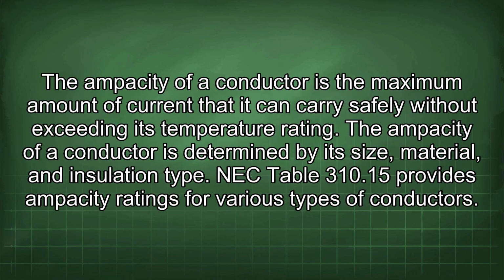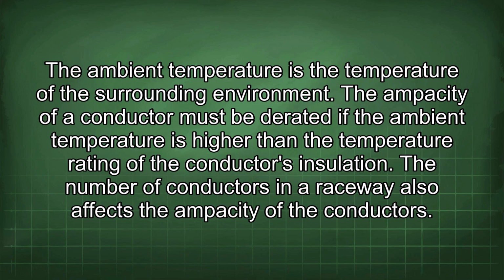The ampacity of a conductor is the maximum amount of current that it can carry safely without exceeding its temperature rating. The ampacity of a conductor is determined by its size, material, and insulation type. NEC Table 310.15 provides ampacity ratings for various types of conductors. The ambient temperature is the temperature of the surrounding environment.